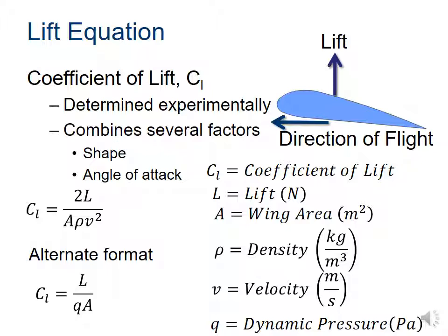Remember from our forces discussion, at equilibrium, the lift must be equal to the weight to maintain altitude. So in this equation, you will use the weight of the aircraft for lift. Again, make sure units are consistent prior to using the equation, meaning you can use SI or customary units as long as they correspond throughout the equation.